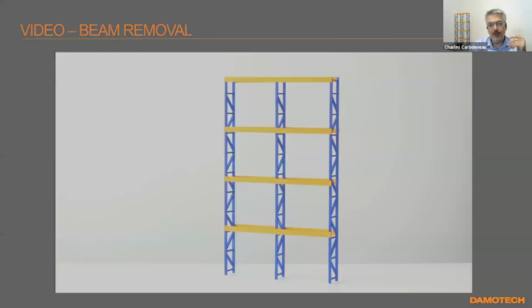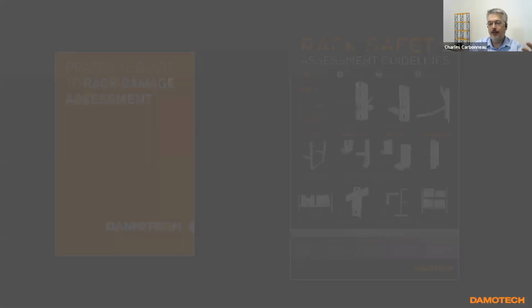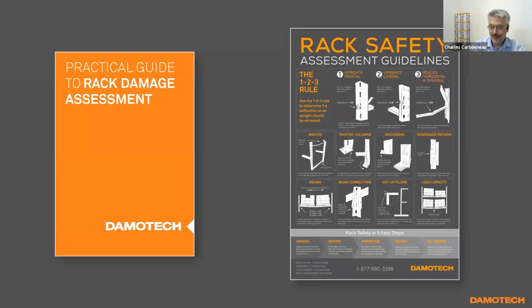And so what happens with this is that we lower the capacity by a factor of 4, not 2. It's a factor of 4 because the length between the floor and the beam is squared in our equation, and it's a divider. So we can see that reality totally matches what we do in terms of calculations. So if you have to move a beam elevation and somebody had a calculation done and said, oh yeah, sure, you can move it 24 inches higher up, and then you can double stack at the bottom for some reason.